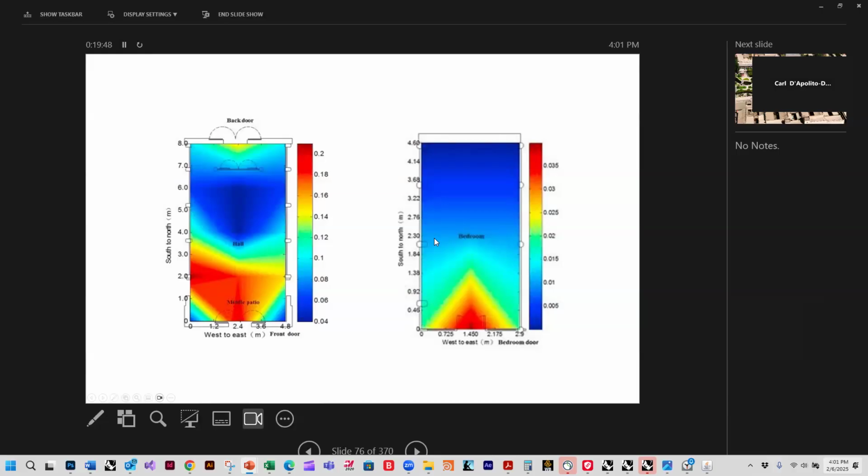So this works on two principles. The patio, the main hall, is ventilated by virtue of just the wind blowing through it. But even the bedrooms that don't have an opening on the other side are ventilated because they have a screened partition and high windows that can be opened, even if the door isn't open.